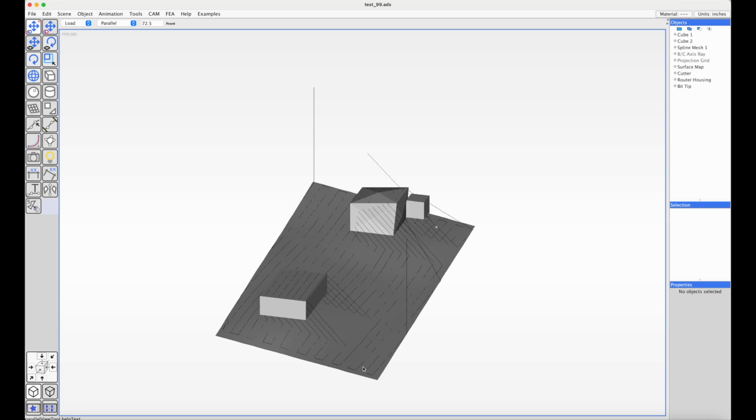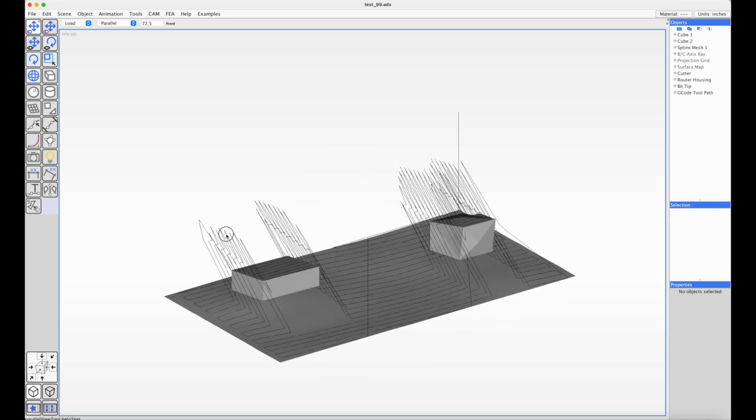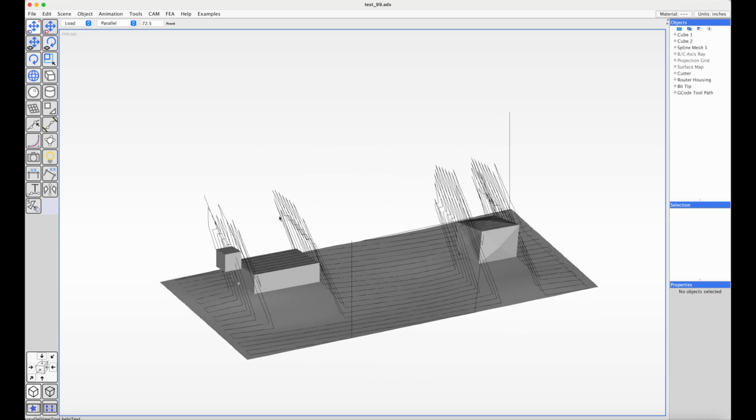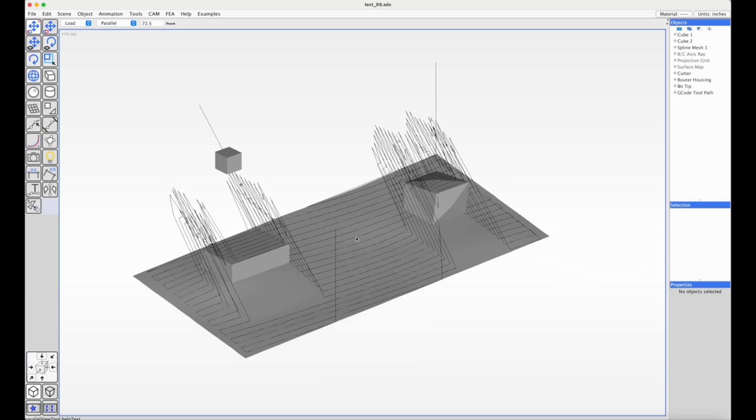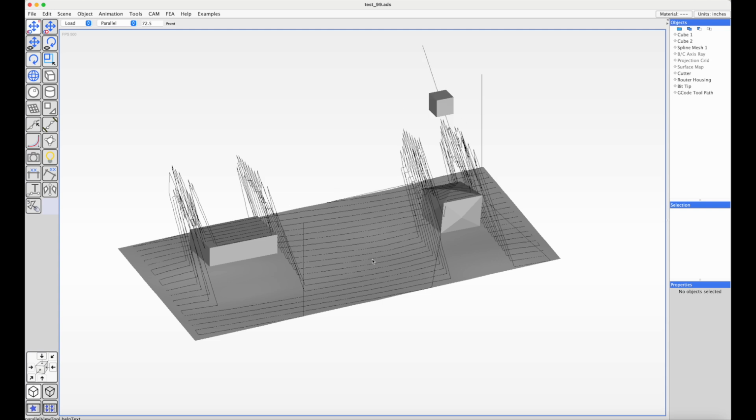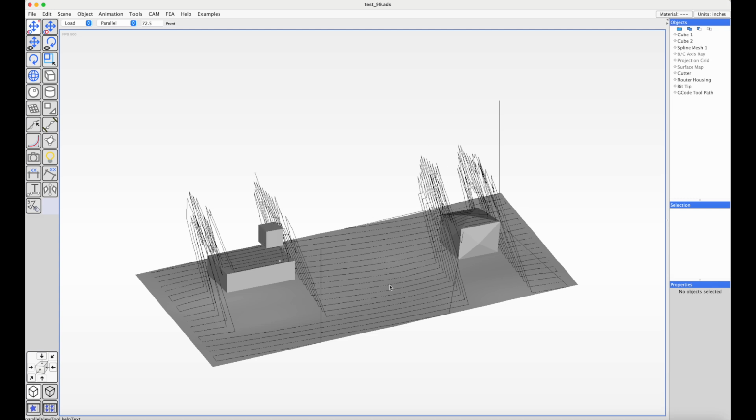So it's mapping points along the surface detected, and now it's showing the tool path, which is based off of the surface, but you can see along the profile, along the edges, it's expanding the region so that the machine doesn't collide with the part. So once it runs through its iterations to remove the collisions, then it will demonstrate the final cutting pass.